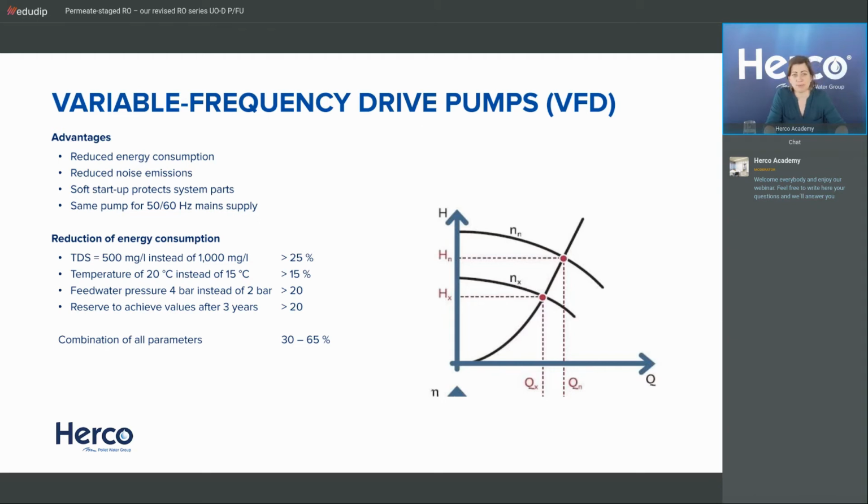Basically, what you need to remember is it is something that happens very, very often, that you don't run the pump exactly at the design point. And it's really worth it to use a variable frequency drive because your end client will save a lot of money with that. So usually we have a payback period of maybe 6 months, 1 year. And after that, you actually really save a lot of money with this unit with a variable frequency drive. Okay,